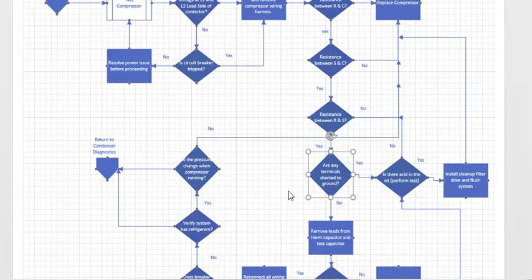Now, before you replace the compressor and before you go through that whole procedure of refrigerant recovery and everything, you want to do an acid check. Is there acid in the compressor oil? There are quick acid check test kits you can get that are very inexpensive and very fast. It has a piece of paper in it that turns color if the refrigerant oil has acid in it.